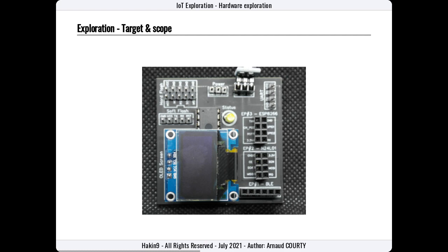You can make some assumptions about this device. Is there a serial connection like UART? Is there live inspection capability like JTAG? Is there an I2C or SPI bus for peripheral connections like the screen or Bluetooth? And is Bluetooth embedded in the SoC? Is there other remote control capability? You have to explore this.